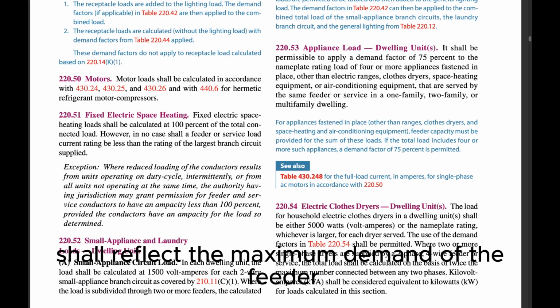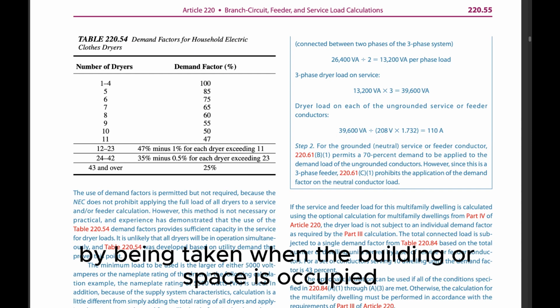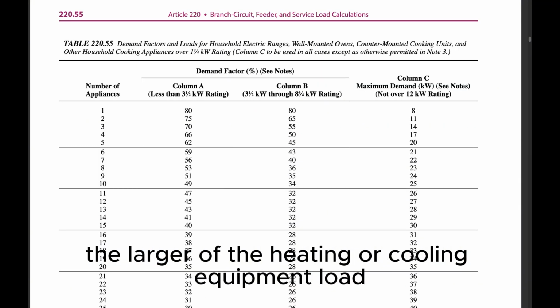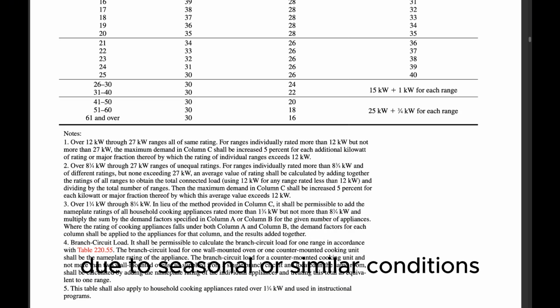The recording shall reflect the maximum demand of the feeder or service by being taken when the building or space is occupied, and shall include by measurement or calculation the larger of the heating or cooling equipment load, and other loads that may be periodic in nature due to seasonal or similar conditions.